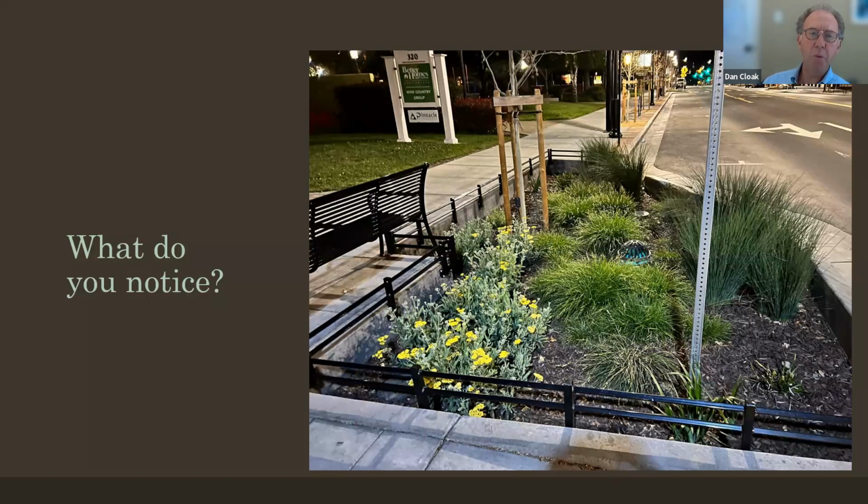Someone noted that in this situation, it would be likely that the soils below are compacted. Yes, almost always in this situation, right? I mean, this used to be street, so it must have been compacted. And you hope that they follow the guidance that's there and over-excavated or at least ripped those soils to promote infiltration when it was constructed. Yeah, and they are using the wood chip mulch, which will float more.